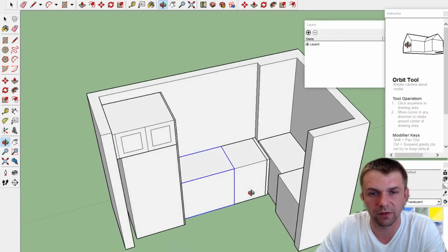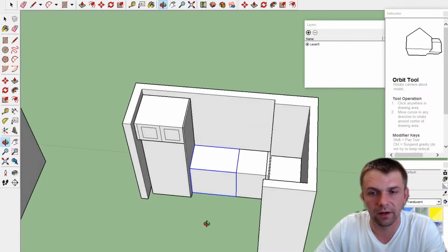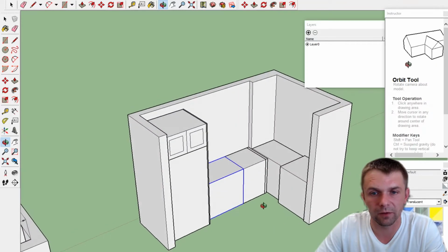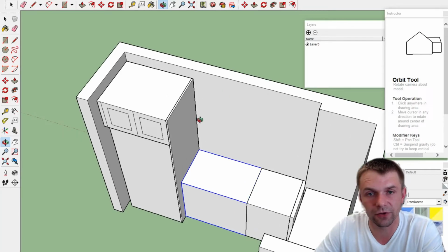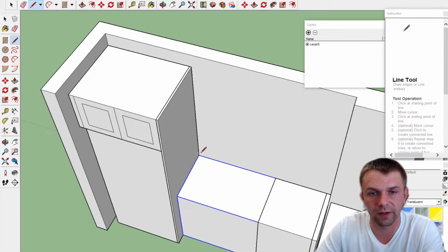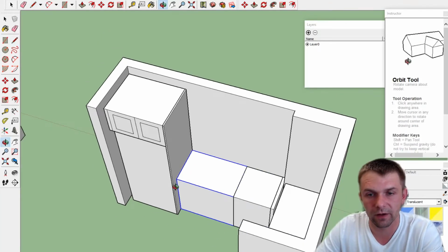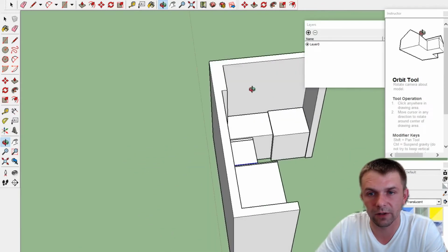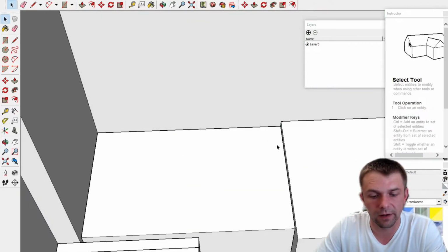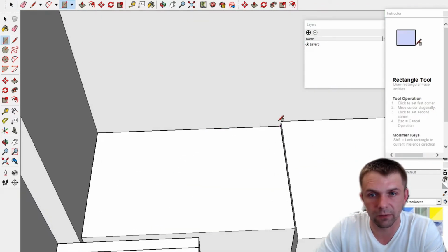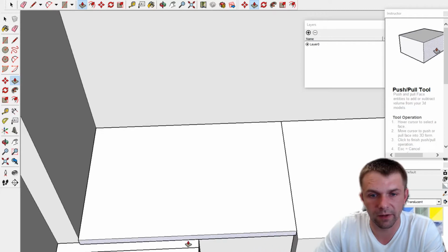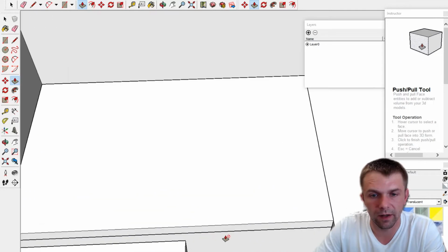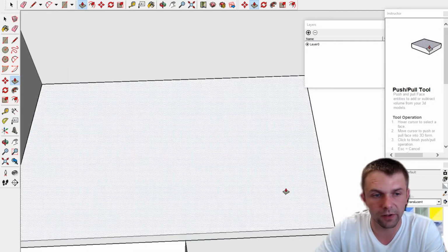So all our bases are laid out, and now we're able to work with this, show it to somebody, show it to a friend, just have a visual of 3D space, how the kitchen looked like, whatever the case is. We can add the countertops to this. Here again, working in blocks, very important. So we select from this point to here, P for pull, go flush with the cabinets, and it goes 1 inch past the doors.